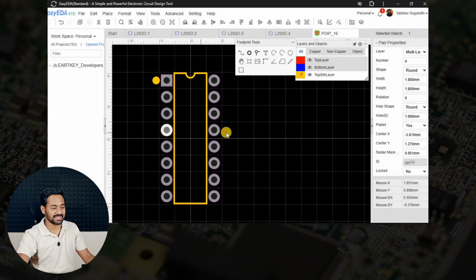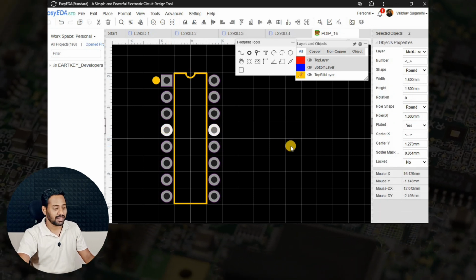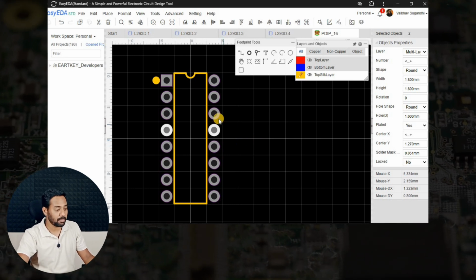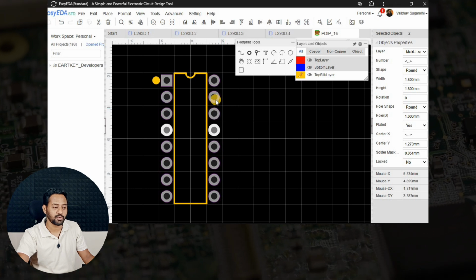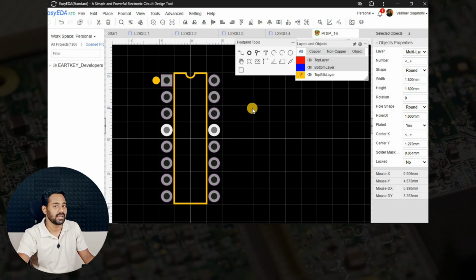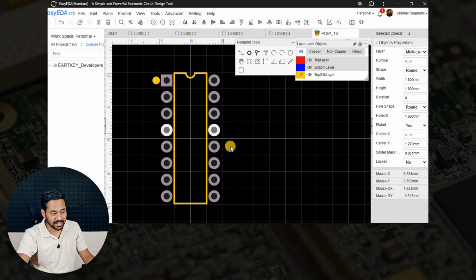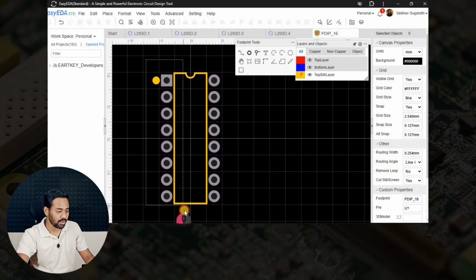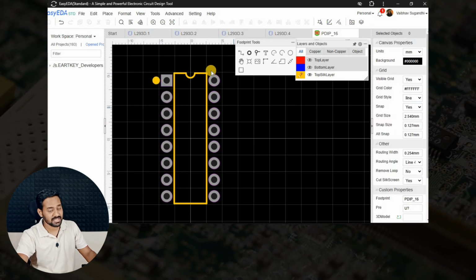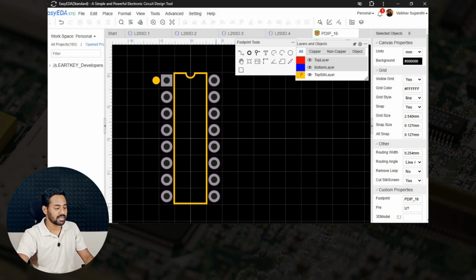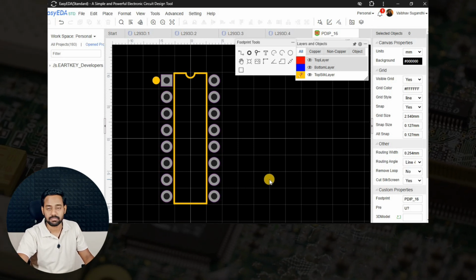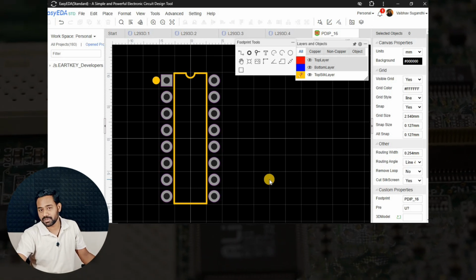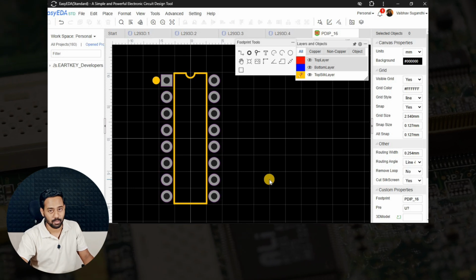The first important thing is these two pins are going to be 1.27 from the x-axis, which is a fundamental, and upon that we are going to add a 2.54, 2.54, 2.54 on the top side. And similarly, we are going to add a 2.54 on the negative y-axis as well. And when we are placing all these ICs and all these pins and this side pins, they are having the 3.81 mm apart from each other, which is absolutely same as a 555 timer example, or maybe the previous tutorial example, which is all about a dual op-amp.